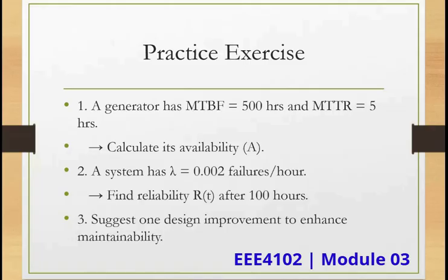So the recommendation can be, for instance, modular cartridge, like we've seen for the case study, whereby for the modular cartridge design for wear components, you can just remove the modules and easily plug in new ones, replace, which makes it easy. And why it helps, it reduces the assembly time and also special tooling, whereby in doing so, it lowers the MTTR.